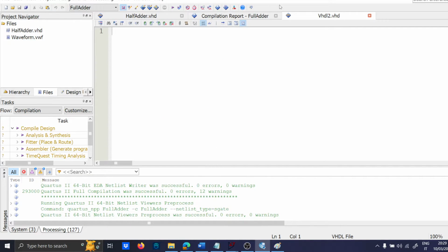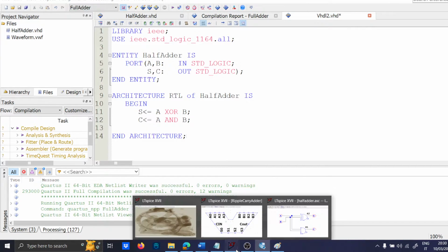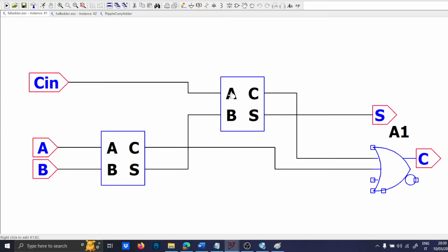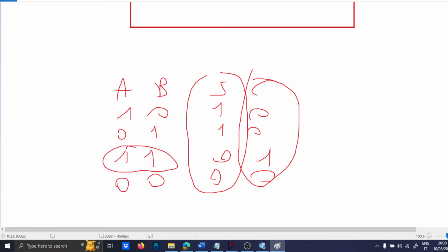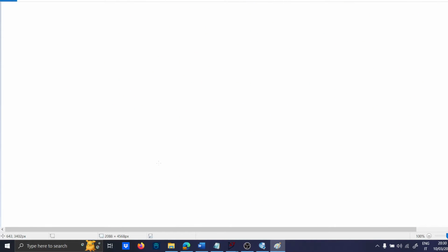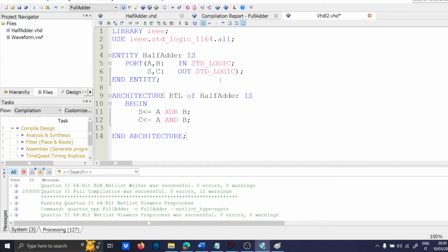So let's open a new file. Let's make a VHDL file, and basically use the same thing again. Okay, the FullAdder, if you remember, is done in this way. So we needed to use two FullAdders and connect them like this. But now the thing gets a little bit tricky, because when you use VHDL and you use these components here, you have to use a syntax called component. You use the syntax component and you perform the mapping. I will show how to perform the mapping.